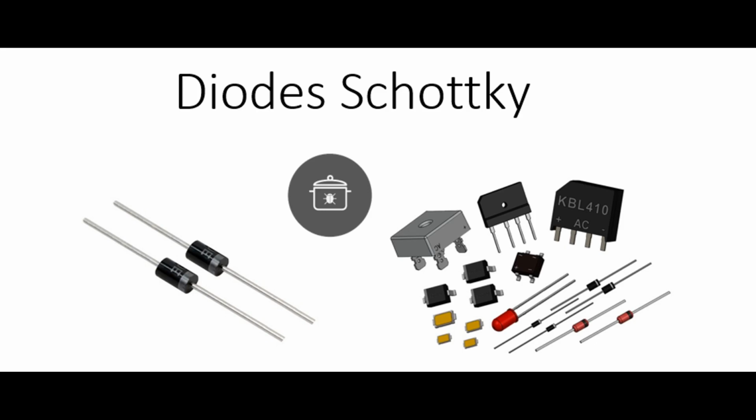Mixers are essential components in heterodyne receivers, where they mix the incoming RF signal with the LO signal to convert it to a lower IF for further signal processing. 2. Detectors. Detectors, also known as demodulators, are devices used to recover the original information or baseband signal from a modulated carrier signal. They are used in communication systems to demodulate signals and extract the transmitted information.